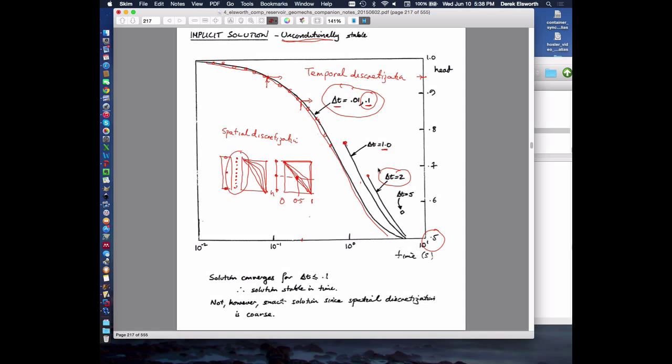If you use a more reasonable, smaller time step, then these results and these results can't both be right, right? So it has to be these ones at the finest time discretization that have to be correct. And so we'd want to be able to use that. But these also aren't correct for the real physical system that we might be interested in looking at. Because these are correct for this two-element system that has a kink in the pressure profile, but not for the true continuum system. And so we need to be aware of the fact that it matters what we do for discretization, both in space and time.